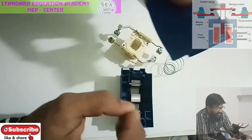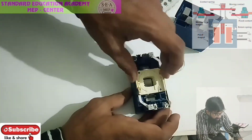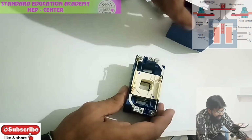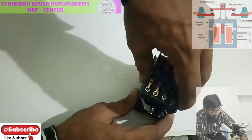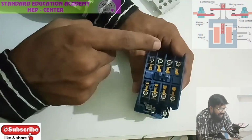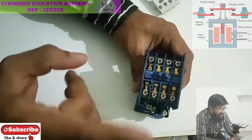electromagnetic field. As I'm placing this particular coil over here, and when I am energizing this coil, automatically what will happen, this particular spring, which will be placed over here like this, will tend to move the moving part towards the fixed part. Due to that, L1, L2, L3 will come in contact with T1, T2, T3. Understand?